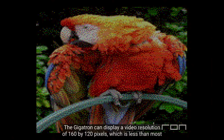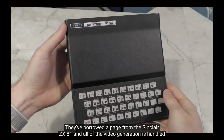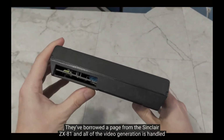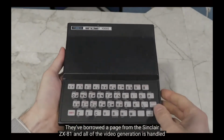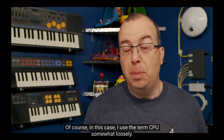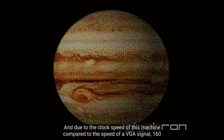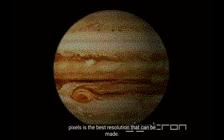The Gigatron can display a video resolution of 160 by 120 pixels, which is less than most 8-bit computers. However, the Gigatron doesn't really have a video chip. They've borrowed a page from the Sinclair ZX81, and all of the video generation is handled in software by the CPU. Of course, in this case I use the term CPU somewhat loosely. And due to the clock speed of this machine compared to the speed of a VGA signal, 160 pixels is the best resolution that can be made.